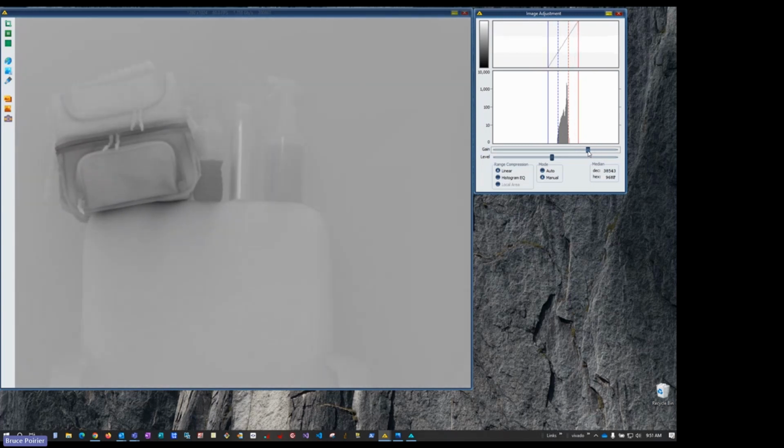You can see that the image is all washed out. We're only using middle gray values, and those middle gray values correspond to the white band in the transfer function graph. And you'll notice that white band is where the automatic calculation of the limits of the transfer function intersect with the manual transfer function.